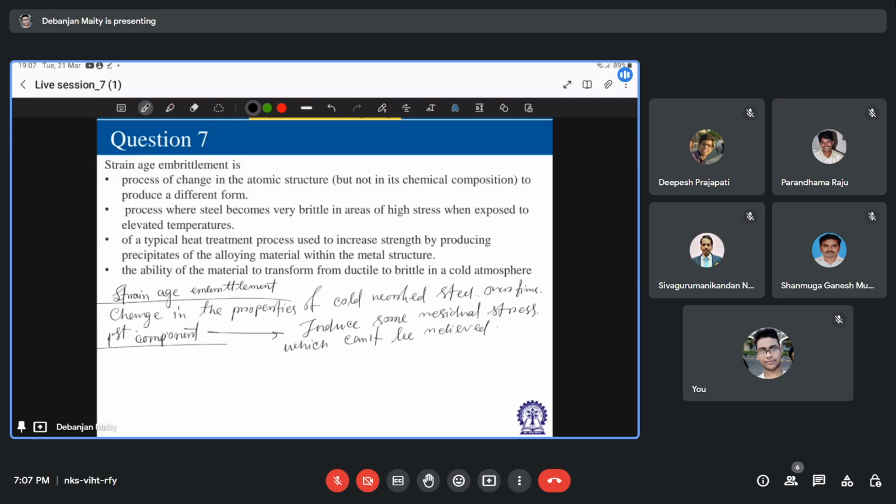Sometimes there can be impurities in the steel, right? Such as those found in some lower quality steel, say used for reinforcing bars. If a part cracks due to strain age embrittlement, the cracking occurs immediately, and is often seen at the job site, as in the case of reinforcing bar.